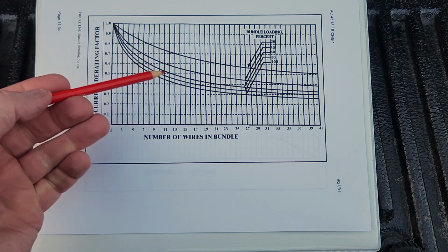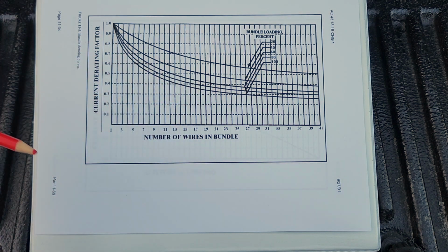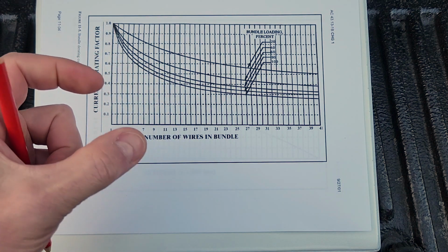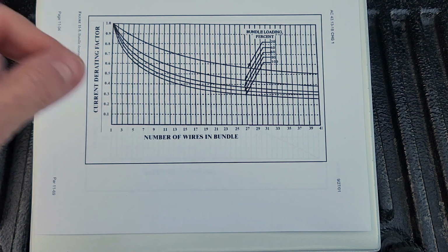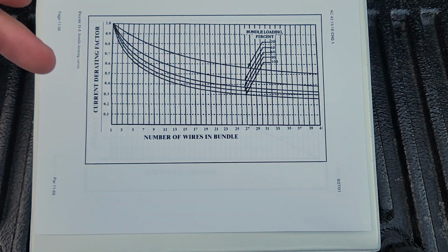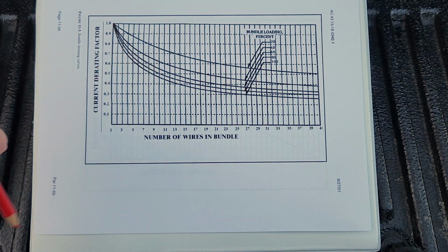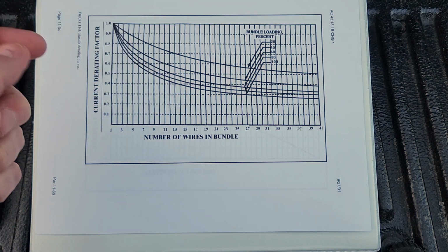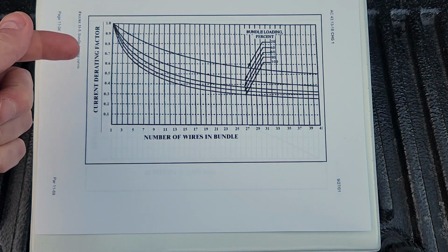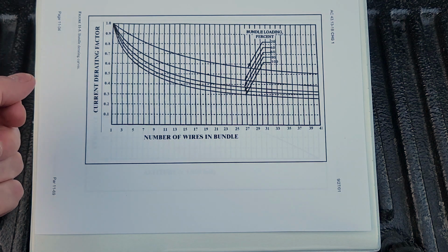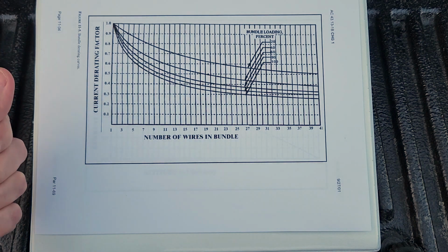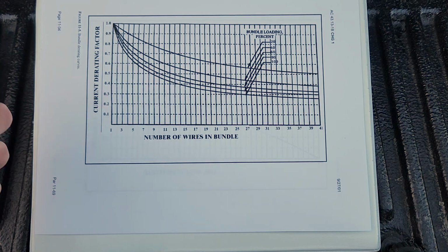All right. So this is mostly important in aviation, not so much elsewhere. But a lot of times you'll have wires in a bundle, and because the wires running on the inside of the bundle are insulated by the wires on the outside, it can't get rid of heat as well. So you've got to derate the bundle. You don't really put less current through it because the loads still need the current they need.